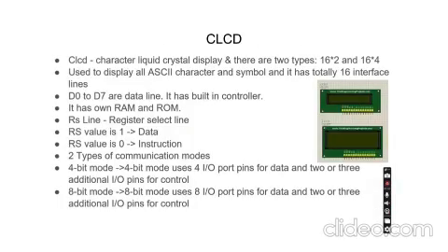Okay, the next thing is CLCD. CLCD is a character liquid crystal display. There are two types of LCD, one is CLCD and the other is GLCD. CLCD is for displaying ASCII characters, in calculators and multimeters and similar applications. GLCD is used for small bar graphs and small images. A bike dashboard is an example of a GLCD. But for this project, we are using only CLCD, not GLCD.